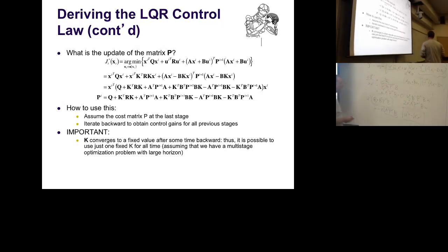This control law I know is going to be optimal, and I know what K looks like. The way you compute it is just not pretty. So fine. That means I can drop the minimization by just plugging in the control law. This is what happens here. ui gets replaced with K times xi, just transposed, so the sequence changes. The same here, we do the same with ui there. So that is now an equation which tells me that my optimal cost at time step i is a function of all that and the optimal cost at time step i plus 1.